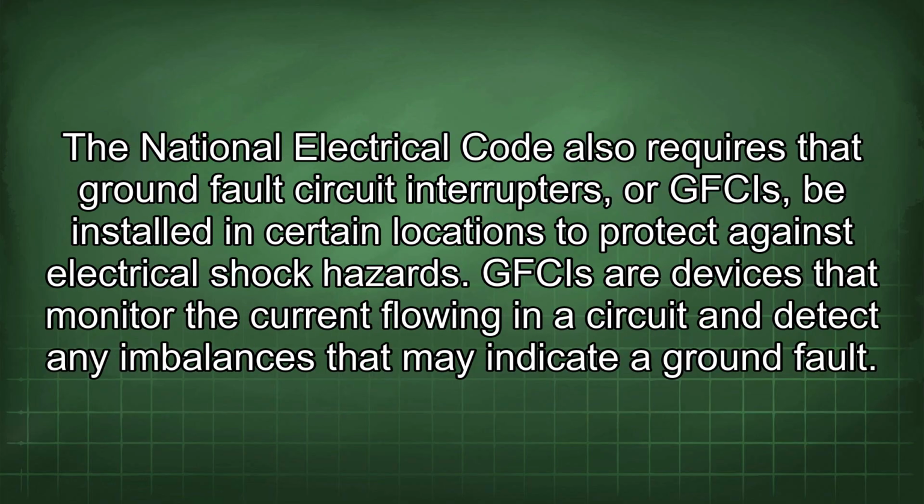The National Electrical Code also requires that ground fault circuit interrupters, or GFCIs, be installed in certain locations to protect against electrical shock hazards. GFCIs are devices that monitor the current flowing in a circuit and detect any imbalances that may indicate a ground fault.